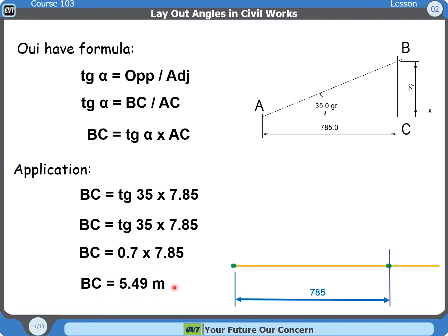To set out point B, we need to start by laying out a horizontal line with a mark of the starting point and the distance of 7.85 meters. We mark it on the baseline. Then from the point at the distance 7.85, we mark a distance of 4 meters on the baseline. Then from this point we take the distance 3 meters, making it vertically.